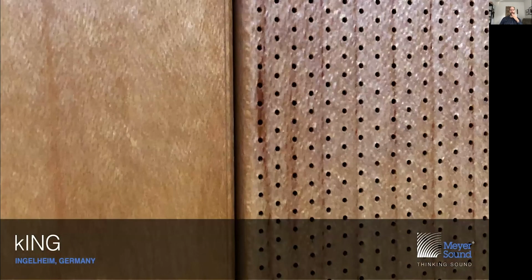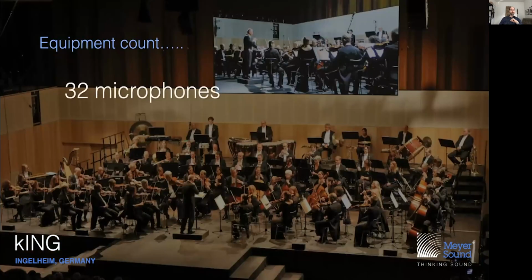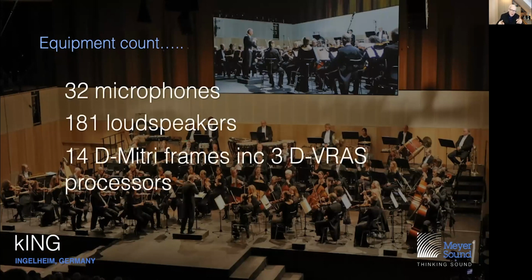So here's a close-up view of the acoustic treatment. It's a perforated wood that does a really good job of absorbing sound. So when you walk into this room and you see that it's all wood, you have this impression that it's going to be very reverberant, but it's actually quite dry. It starts at about 0.8 seconds, and with Constellation, we bring it all the way up to 3 seconds for choral performances. And just one thing to chip in, Pierre.